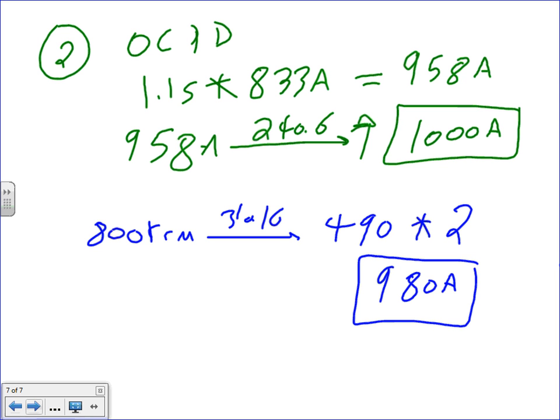You have 2 options: either you up your conductors to 1,000 or lower the overcurrent protection device to handle this. If I decided to go down, it goes to 800 amp.